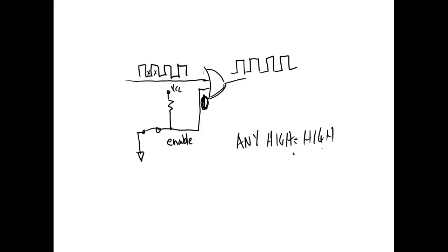And it all depends on what type of light. It all depends on who's down here. What do they need down, whoever this guy feeds, whatever it needs. If I come up here and add another input, then we can disable it with one input. If I enable it, it acts like a 2-input OR gate. So if I had 4 inputs, I could use one for it to enable, and then when it's enabled, it acts like a 3-input OR gate.